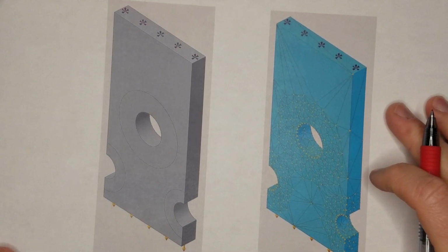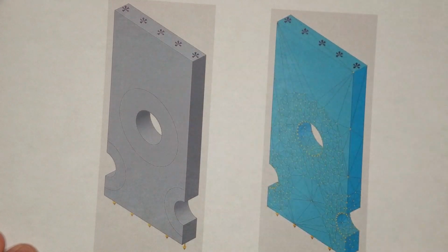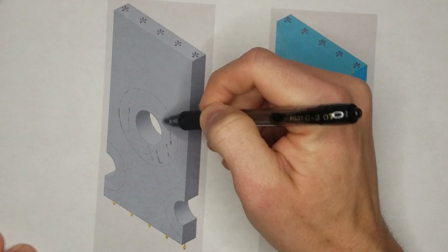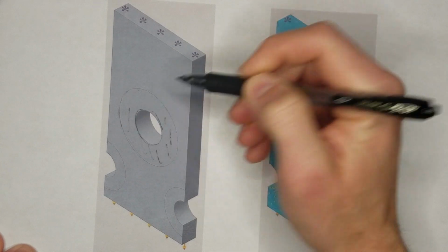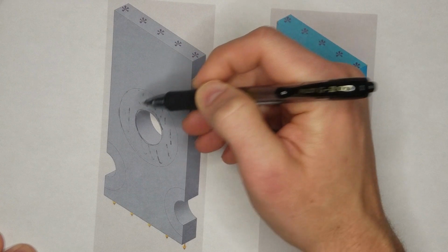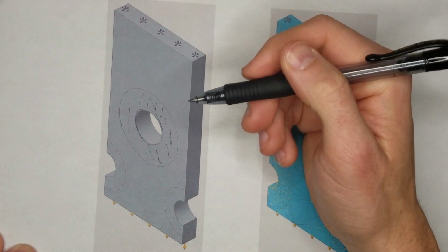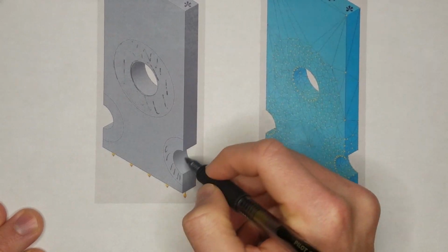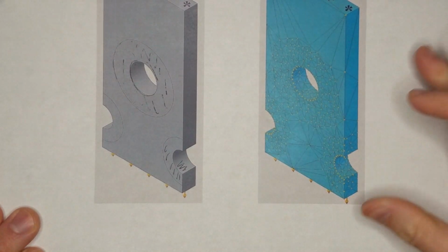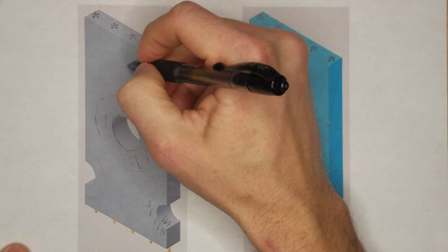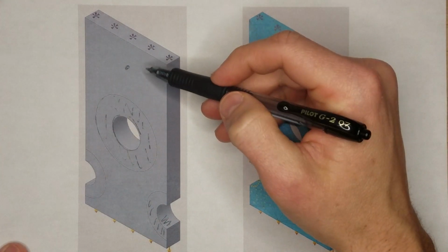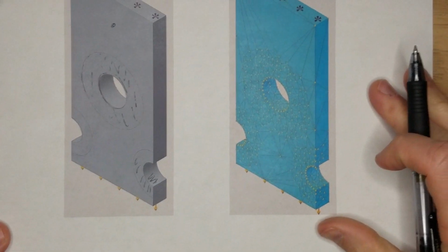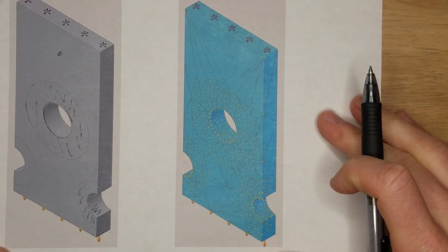Okay, I've got this same bar here, but you can see I've assigned a region to it around this hole, and I'm going to say I want really good mesh all in here, and I want good mesh around this curve. There are some controls in the software that you can apply to get that. And I want good mesh in this region, and I want good mesh in here. And I don't care so much about what my stress is right there. It's not going to be maximal, certainly not compared to my notches here and my hole. I know that. So this is what the mesh could possibly look like.